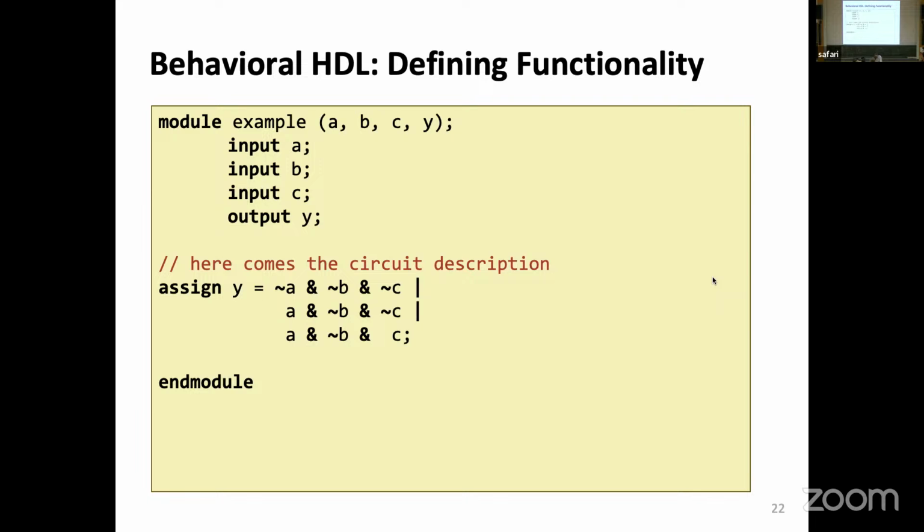There are many very legitimate reasons to do this. The first thing is to divide the complexity between people, right? To say, hey, there's an ALU, there is an instruction decoder, you write the instruction decoder, I write the ALU, and then at the top, the instruction will combine them. And in that type of complication, you might want to use tricks of the tool to limit certain things to certain parts of your circuit. You say optimize this differently than that. And for that, having a structure helps because you can identify parts that you want to have.